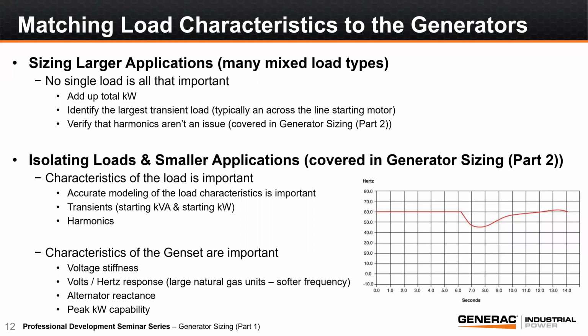The second way to look at sizing is looking at different unique characteristics of a particular load, such as soft starters or VFDs. This is something that is covered more in the second module that we can hopefully do at a future date with you all. So back to the whole building. The great thing about Power Design Pro, which is Generac's sizing tool, is that you can take the peak demand from the utility bills or power analysis tool and then enter that into Power Design Pro.